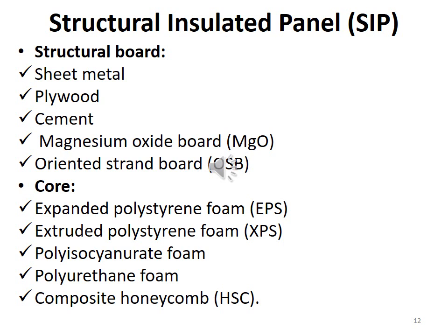The structural insulated panels use fiber cement or plywood sheet for the panels and agricultural fiber such as wheat straw for the core. The third important parameter of structural insulated panel is a spline or connector piece between SIP structural insulated panels. When you are going to join or fabricate structural insulated panels, you need three components. The first one is the structural board, the second is the core, and the third one is the connector piece.